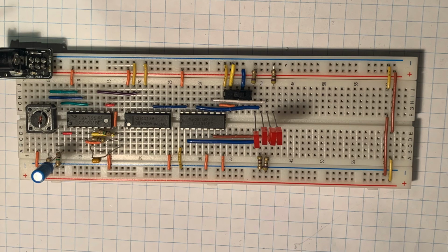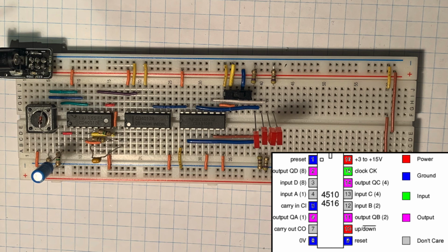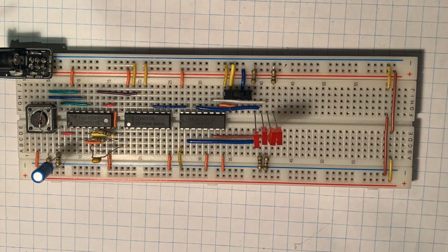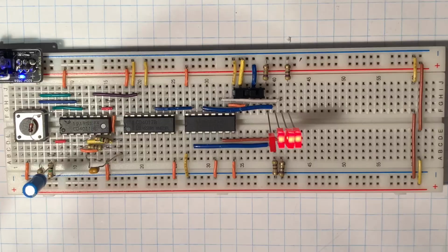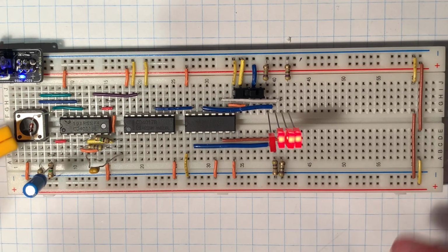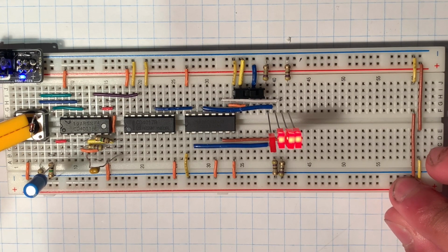This next step converts the ring counting output into a binary counting output from 0 to 9 and repeating. This can be achieved by connecting the 1, 2, 4, and 8 outputs of the 4017 chip to their corresponding 1, 2, 4, and 8 inputs in the 4510 chip. The 4 outputs of this chip are then connected to 4 LEDs ordered smallest number to the biggest from right to left. The product will be a counting circuit in binary, counting numbers from 0 to 9.